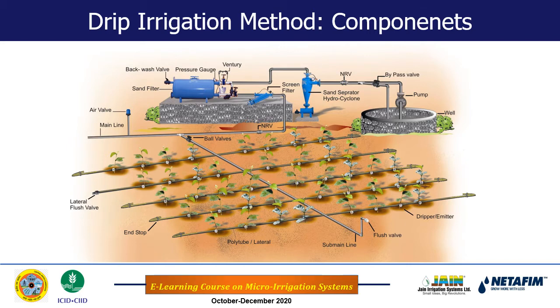and we have to monitor the pressure. For monitoring, we have to measure the pressure, and especially across the filter there is a necessity for a pressure gauge. If the pressure drop across the filter is beyond the desired limit, it shows us that this is the time the filter should be maintained and cleaned. It also shows us the pressure at different points, and if the pressure is less than desired, then we have to take corrective measures so that the pressure is as desired.